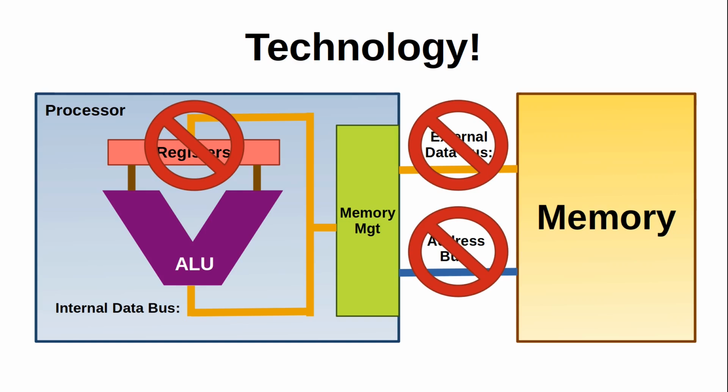So making a 16-bit computer with a 16-bit external data bus was a lot to ask. It was a lot harder to source parts for that, and just harder to build. So we just didn't do it. We used an 8088 or a 65816 and had a processor that was internally 16 bits, and then could interface with 8-bit data outside of the CPU.